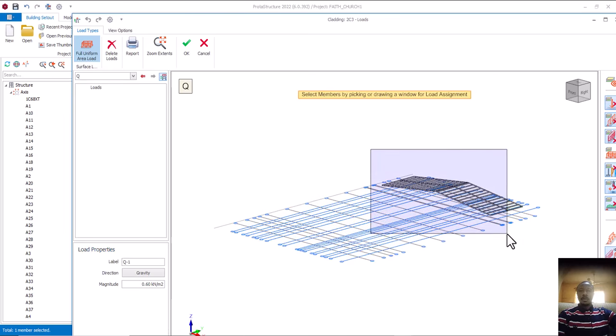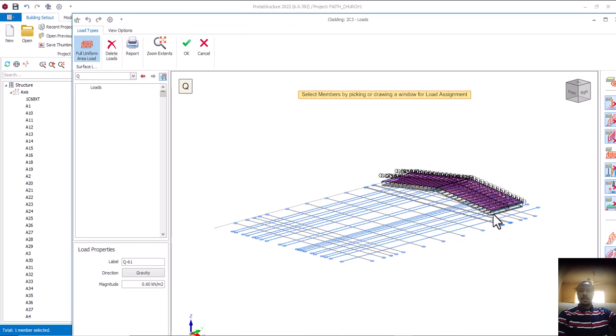I'll come here now and highlight it, and let's leave it there and let it come up. Can you see now? So loaded. That's according to Eurocode when it comes to live load. Is that okay? Because this one is for maintenance. Definitely there will be maintenance. Maybe people will climb the roof and try to add one or two things, let's say a solar panel or any other thing. So this one takes care of that load. Are we together now? This particular value takes care of that particular load.